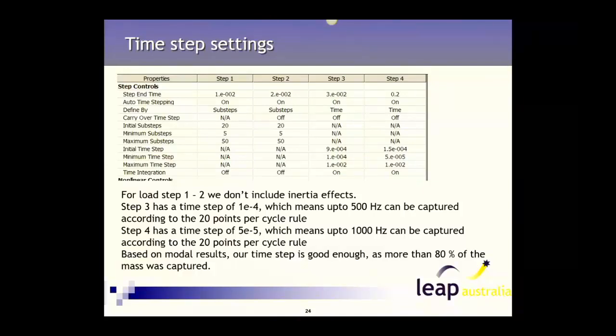Normally, after you've switched them on, I've not seen them switched off. Generally it's almost like a preload step, or getting your initial conditions imposed on a transient, and you can do that with time integration off. So this is a much more efficient solution in terms of solve time.